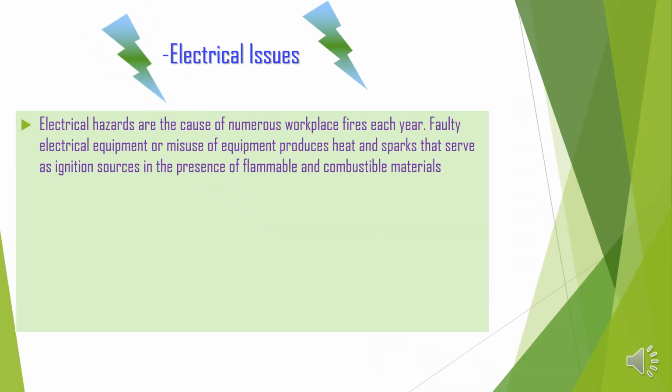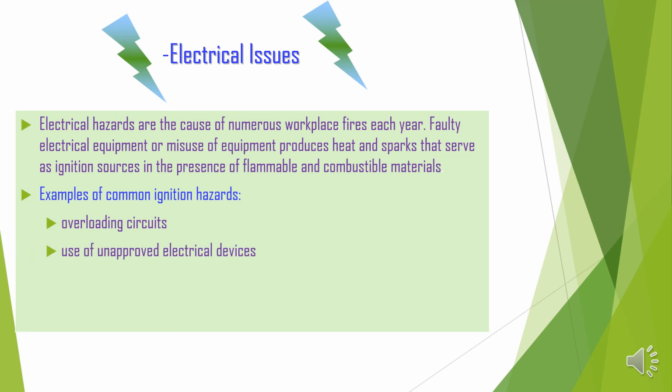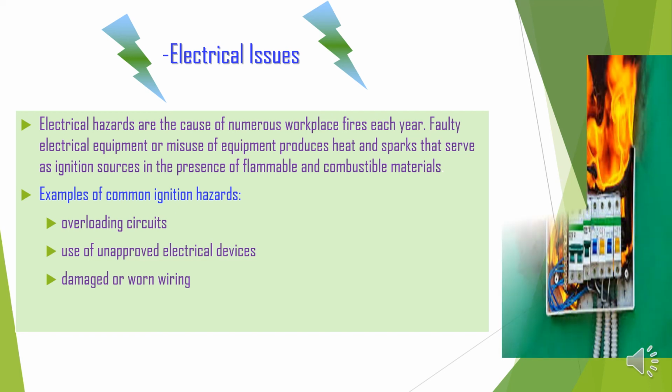What about electrical fires? Is it famous? It's happening. I believe we had one in a hostel a month ago in the Al-Confoda region. Electrical hazards are the cause of numerous workplace fires each year. Electrical equipment or misuse of equipment produces heat and sparks that serve as an ignition source in the presence of flammable and combustible materials. Examples of common ignition hazards: overloading circuits, use of unapproved electrical devices, damaged or worn wiring.